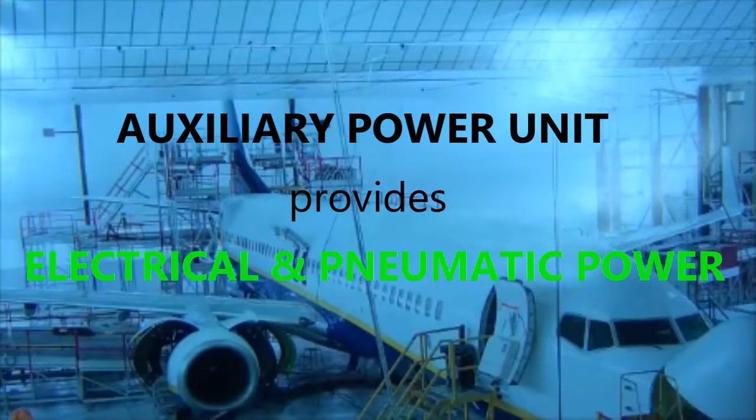Okay, let's get into a little bit on the power section. I mentioned the load compressor air coming in. I'm going to talk about the air intake system in a little bit. Right now I just wanted to section out the APU. Your power section is where you have the compressor. The compressor has diffuser vanes in there. It has different kinds of vanes, and you have an impeller. These components are part of the compressor, specifically engineered to take in that air a certain way, because it needs to be ideal in order to get into the next section.